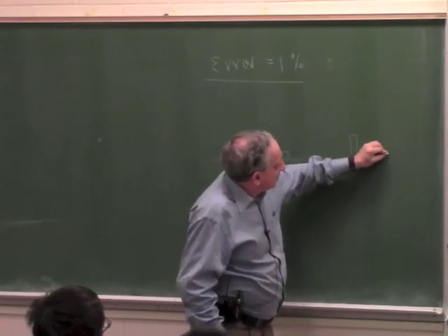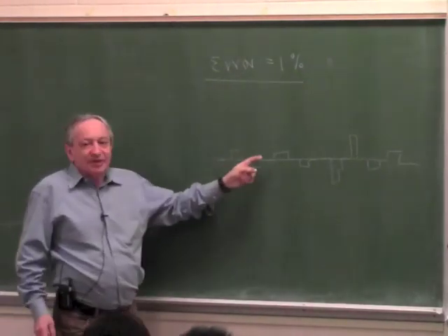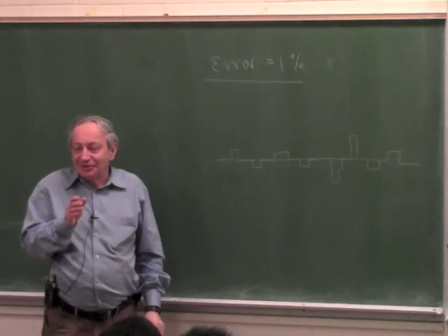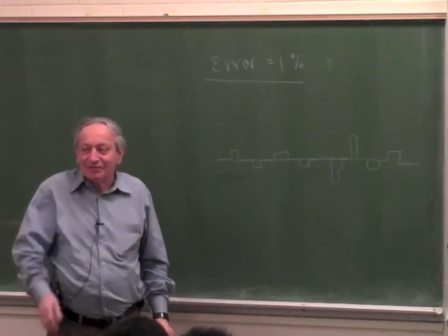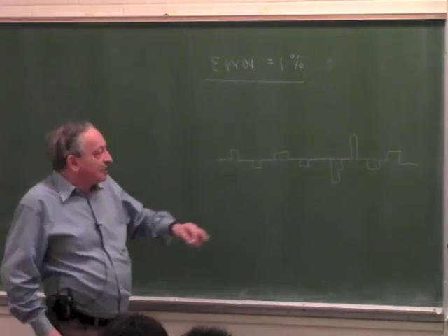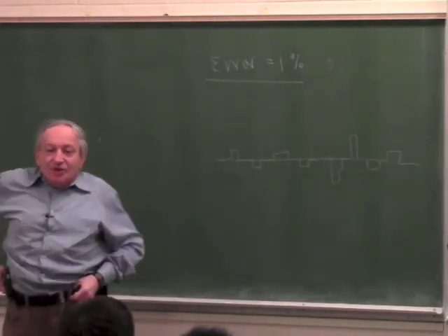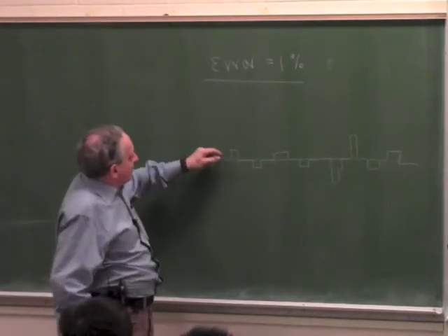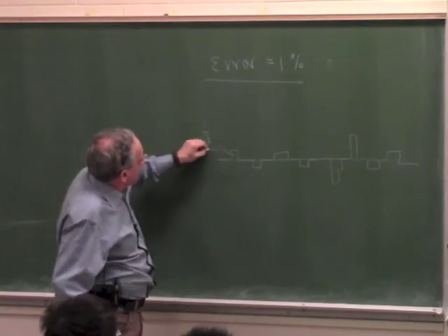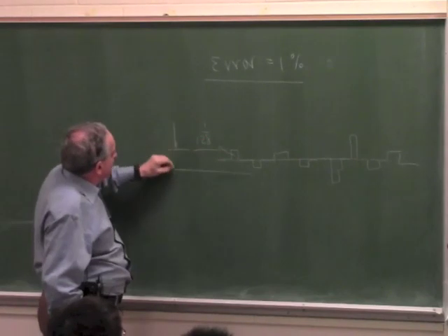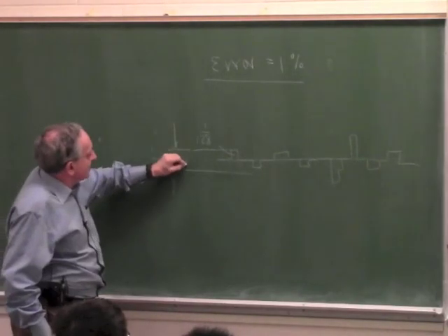So when you look at an output of a digital servo, at the best case, it will be plus minus 1 bit, because it has to hunt. And because you can't fall exactly in the middle of a bit. Say when you are between 2 bits, it will hunt plus minus. But actually, most of the time, it actually hunts 2 bits, because of delays and things like that. So even if it hunted 1 bit, and this is 1 over 128, so full amplitude, already the peak-to-peak error will be 1 over 64 of the full amplitude, which is 1.6%.